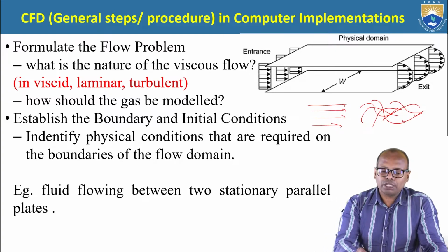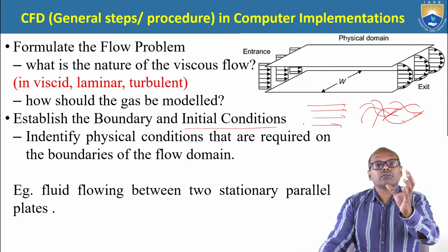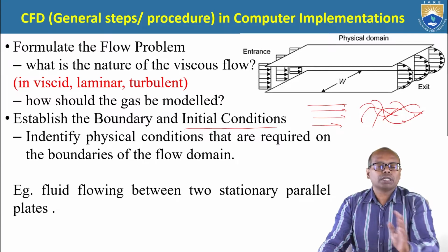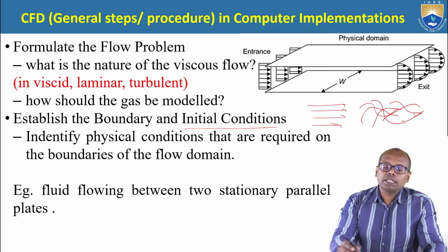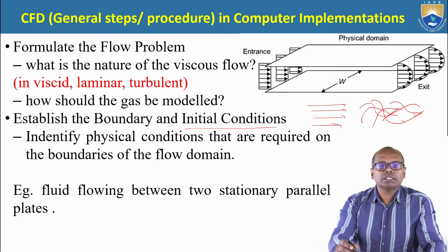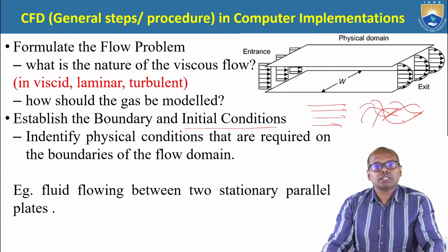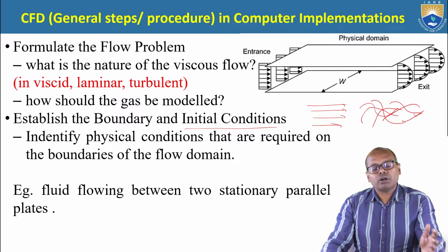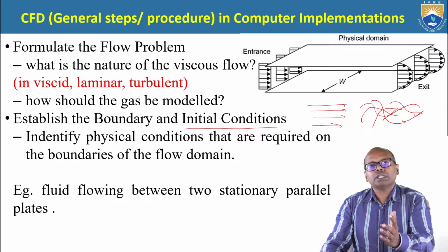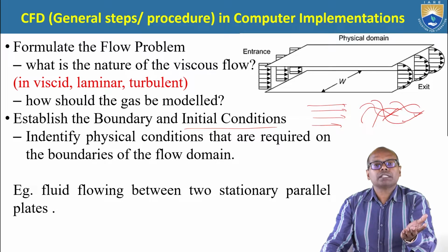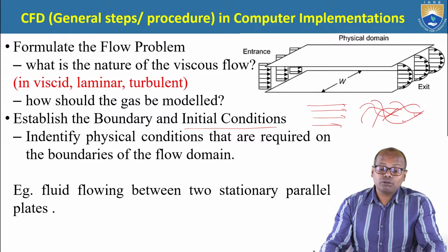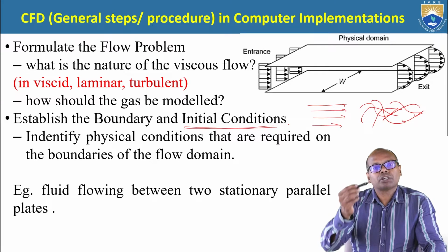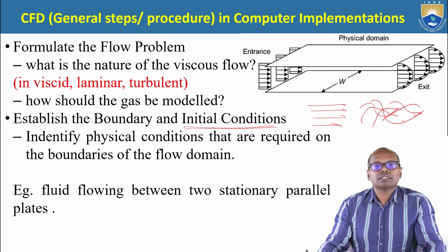The other way also, say suppose I am doing one analysis like the fluid flow analysis. Already I have done this analysis with some velocity. Now I am doing this same analysis with another velocity. Now what I can do is I can give the previous CFD results as the initial conditions for the present one. So that is the way you can simplify or minimize the time taken for the analysis of the solution.